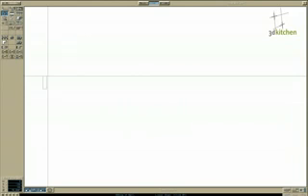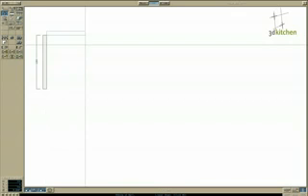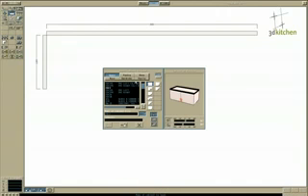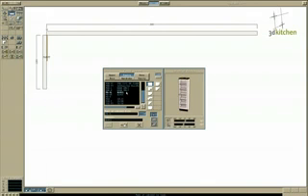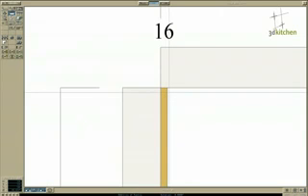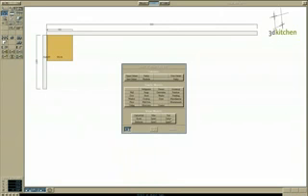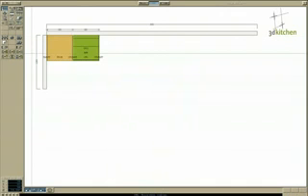So the first step is to add some walls to the design. These can be placed in any direction, any length and any angle. After the walls are placed, we just start adding in components. So we're starting with a panel end, and then we just select the cabinets one by one to add in